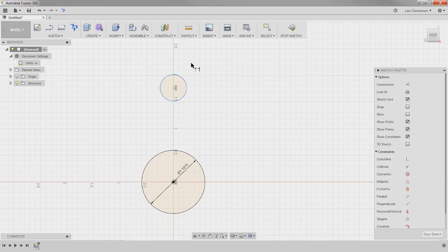If you right click right now, you get an option down here to select the tangency. By default it will always be on center, like it always has been. So make sure you are in the dimension tool, right click, and if I select tangency, it's going to place that tangency on the outside.